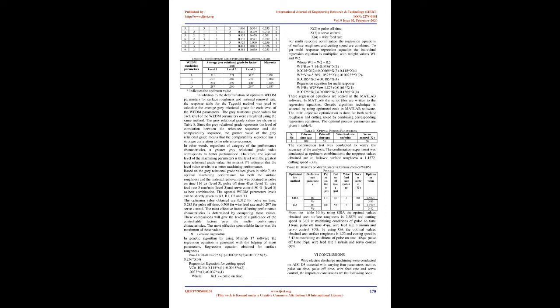Max equals 1.00, min equals 0.00. If all the process parameters are of equal weighting, then it is 0.5. The gray relational coefficients and grade values for each experiment of the L9 orthogonal array. According to the performed experiment design, it is clearly observed from Table 7 that the WEDM parameters setting of experiment number 1 has the highest gray relational grade.